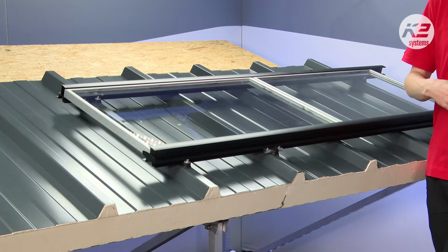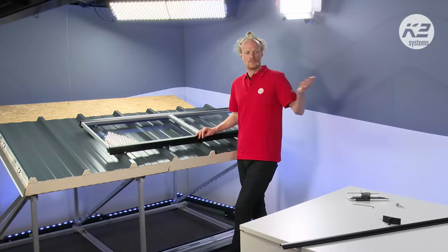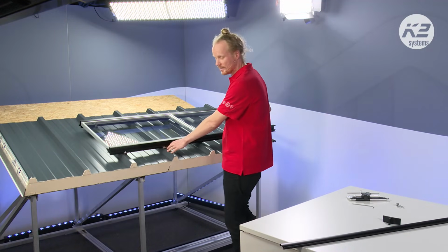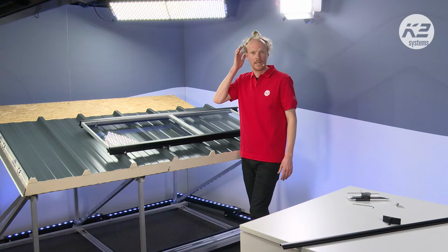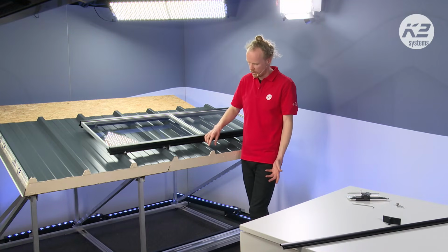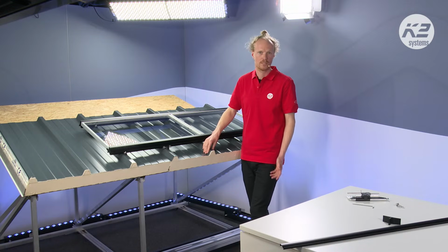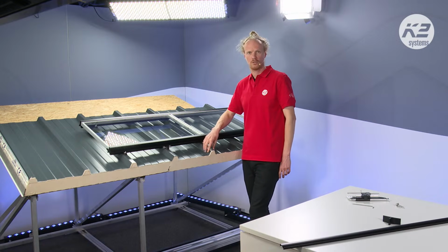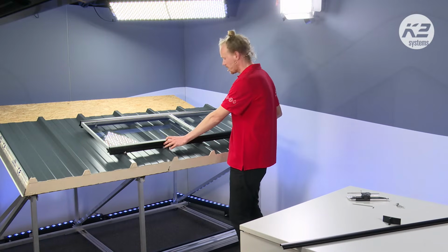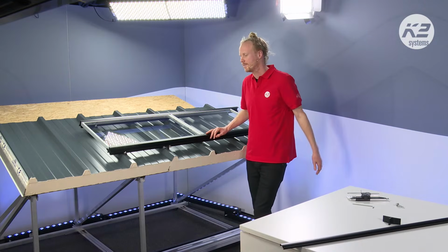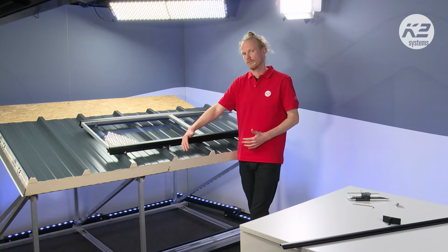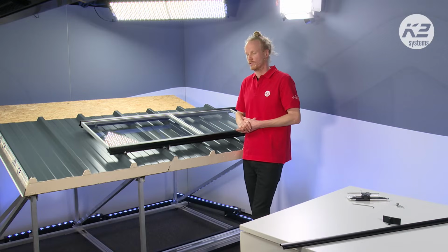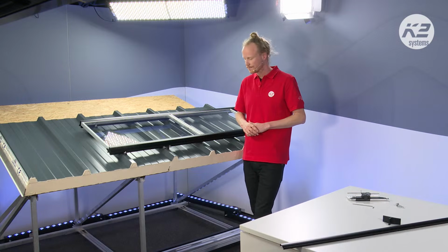So some of the questions that we'll go through later, or later we'll show as well, like how do we decide where to put these base clips? So these are all determined in the base software, depending on the strength of this material, because we are only fixing into the sheeting. If we have a thicker, stronger sheet, then maybe we need to do every second or every third crest. If it's not so strong, maybe you need to do it on every crest. The wind and the snow, all of this is incorporated into the software as well.